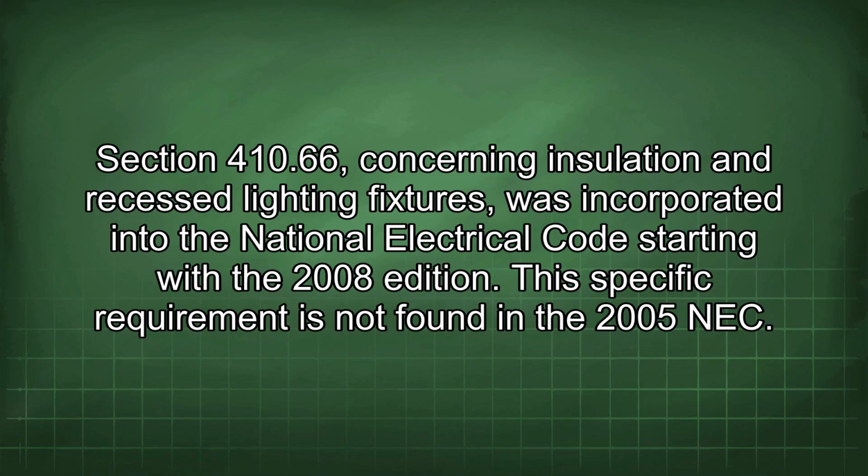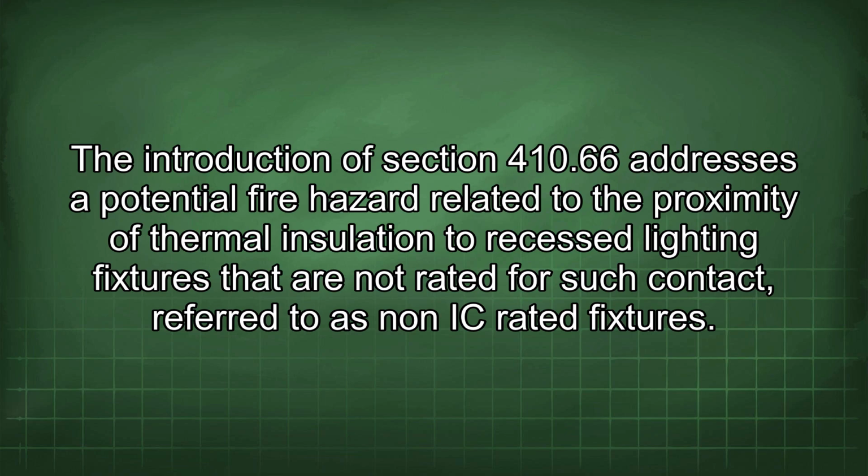Section 410.66, concerning insulation and recessed lighting fixtures, was incorporated into the National Electrical Code starting with the 2008 edition. This specific requirement is not found in the 2005 NEC. The introduction of Section 410.66 addresses a potential fire hazard related to the proximity of thermal insulation to recessed lighting fixtures that are not rated for such contact, referred to as non-IC rated fixtures.